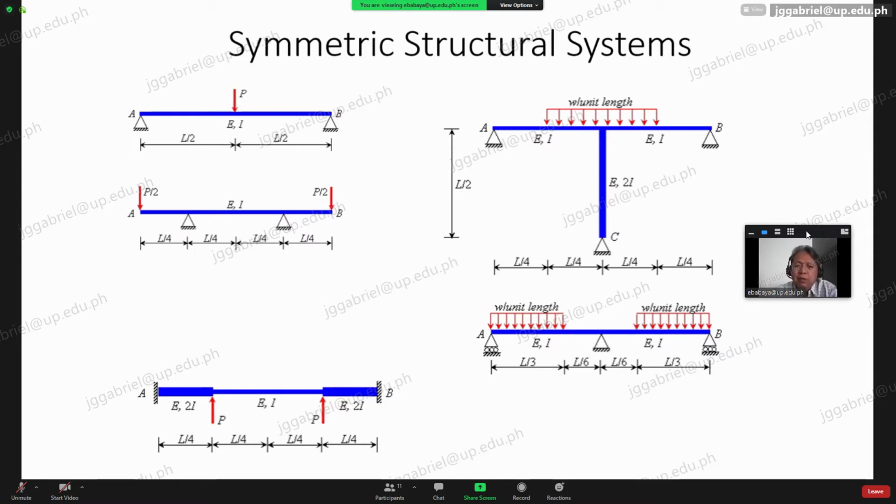So, what influences the deflection of a beam? What has the greater influence on the moment of inertia of the beam? Because of that equation, you can tell it is the H. If you increase the H, the moment of inertia increases cubically. So the height is very important in controlling the moment of inertia.